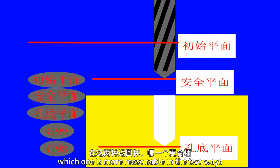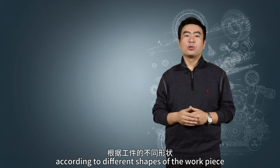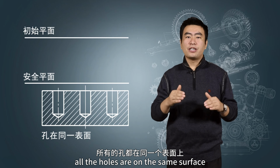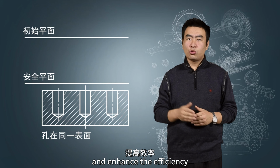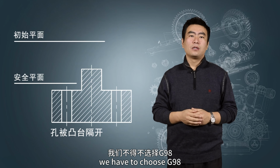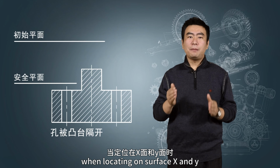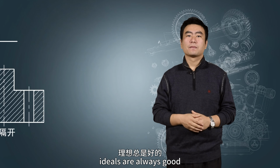Which one is more reasonable of the 2 ways? It requires us to choose according to different shapes of the workpiece and the actual situation of the process. For example, when processing such a workpiece, all the holes are on the same surface, so choosing G99 can reduce the cutting in vain and enhance the efficiency. But when processing this workpiece, we have to choose G98 so that the cutting tool can avoid the boss in the middle and the collision when locating on the XY surface by returning to the original height. It's a safer way.